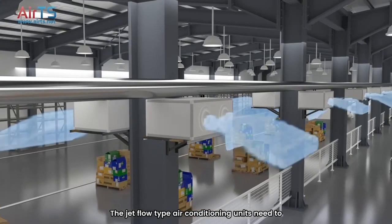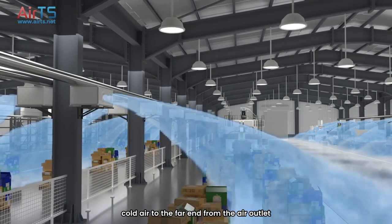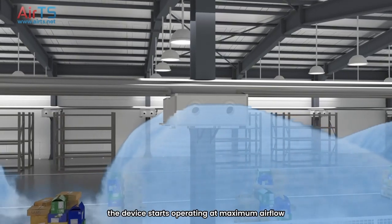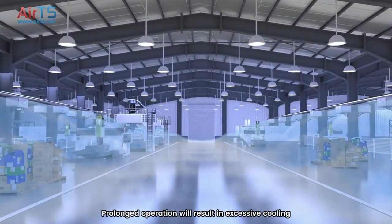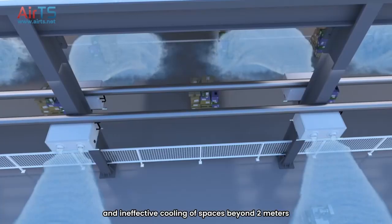The jet flow type air conditioning units need to operate at maximum airflow in order to deliver cold air to the far end from the air outlet. It cannot be adjusted with variable frequency control. The device starts operating at maximum airflow and cooling capacity when it is turned on until it is shut down at the end of work hours. Prolonged operation will result in excessive cooling, causing a decrease in temperature and ineffective cooling of spaces beyond 2 meters.